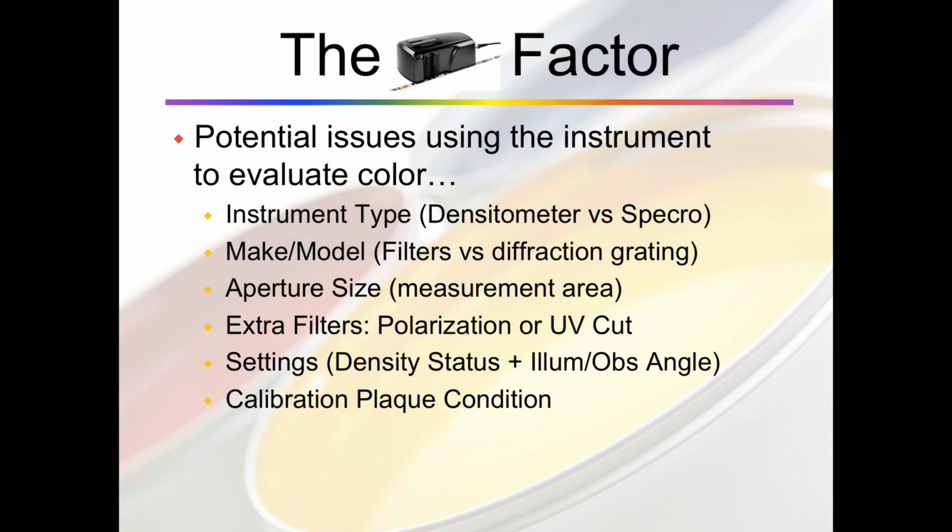Calibration is a critical factor. You must make sure your instrument is daily calibrated, and that's only a valid step if your calibration plaque is clean. So it's very important to monitor the calibration plaque condition, make sure that it is as clean as possible, that there is no dirt, smudges, and you should also follow your instrument manufacturer's guidelines for the proper cleaning technique of that calibration plaque. Each manufacturer will have their own suggestions for the proper upkeep to maintain proper measurement.